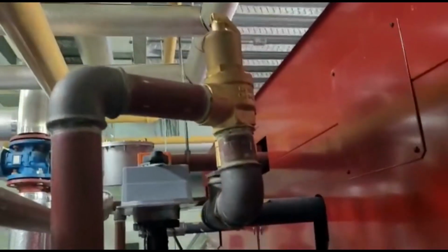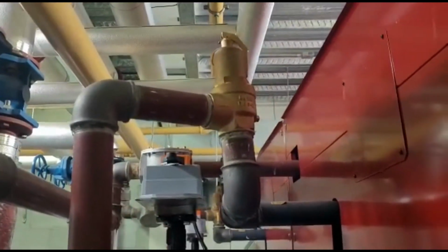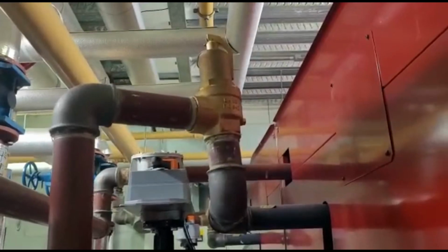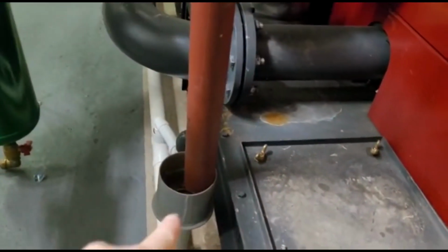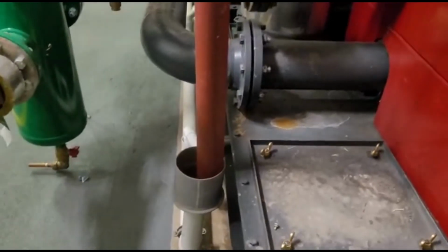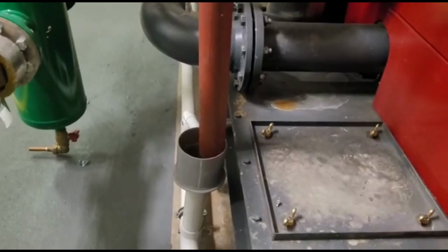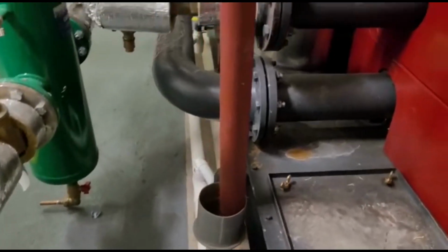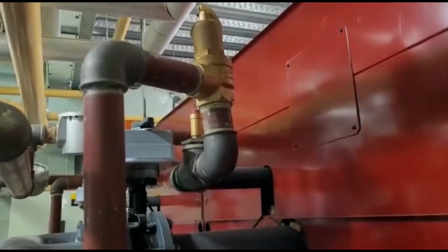Let's move down to that. Alright, so you've got your pressure release valves. The only thing I don't like about these is the way they're being piped up. I don't like them going into cups, because if they start passing, you're going to notice a bit of steam coming out at that, but I like them free flowing to the floor, so they cause a nuisance, and then you know that you've got problems and it's over pressurised.